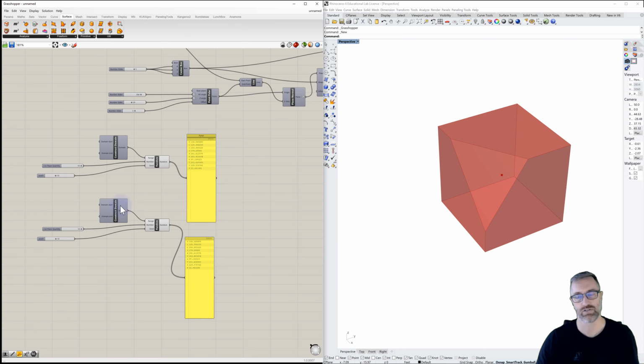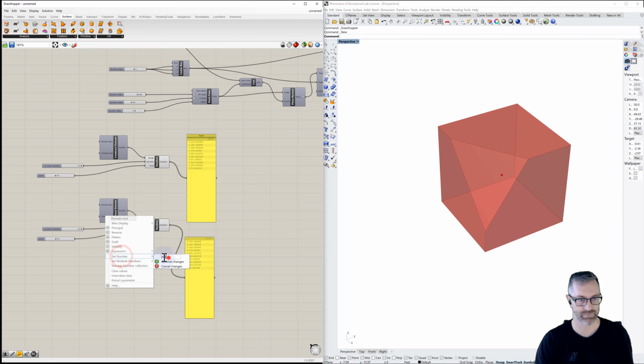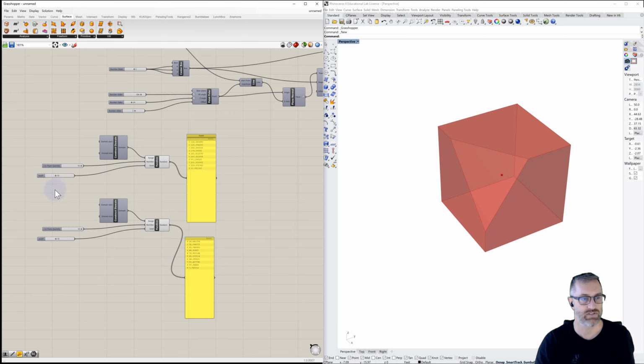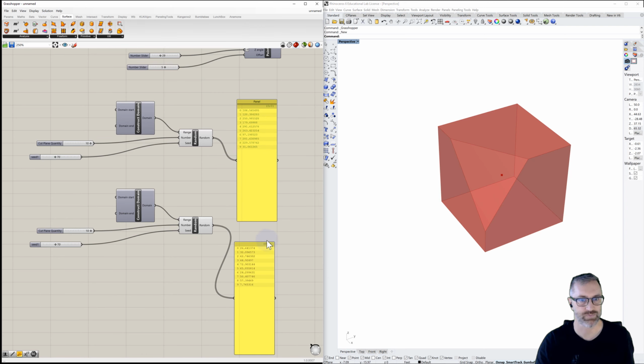And for the second range, what we used before was 0 to 90. So this is already set to 0. We can change the other domain to 90. And it'll go from vertical to horizontal as it rotates around. We'll leave the 70 set there. We can see it's actually generating a different set of values because it has a different domain. The cut plane quantity we can reuse, so that's consistent between them. So if we dial this back, we can see it dials all of them back.